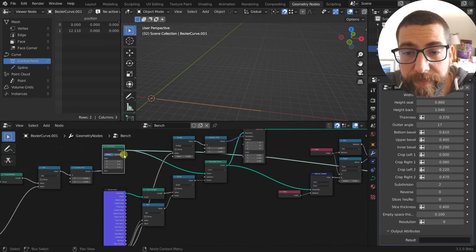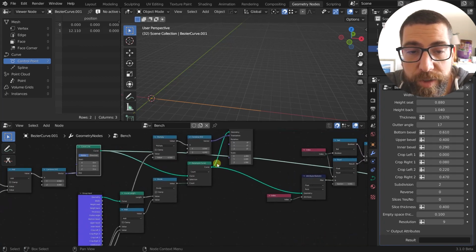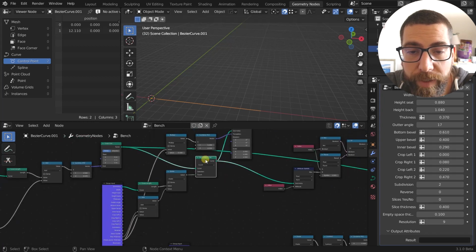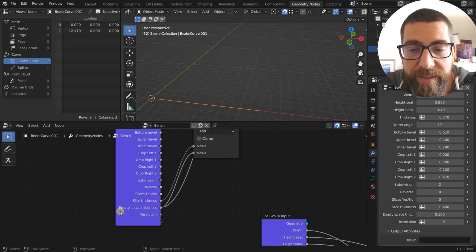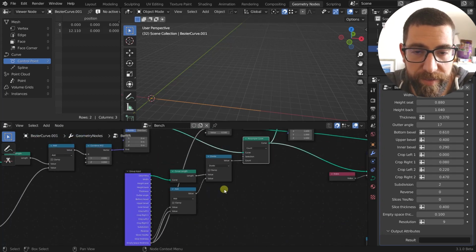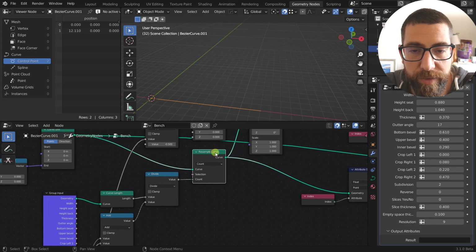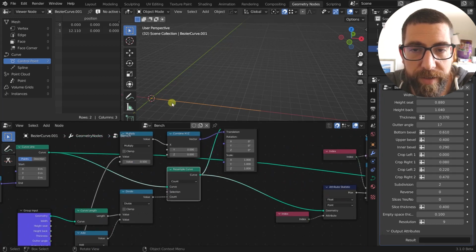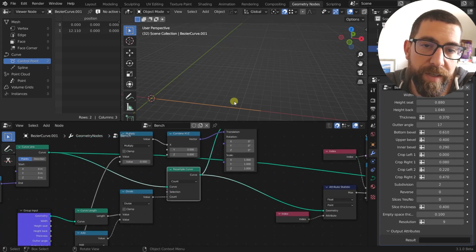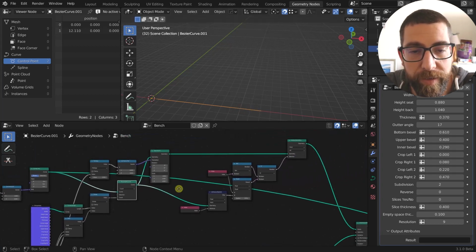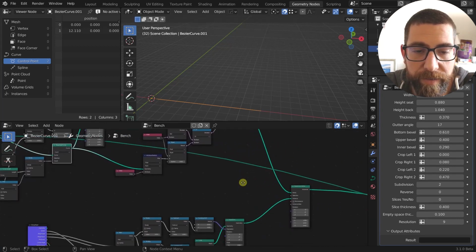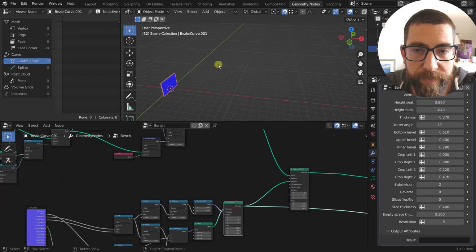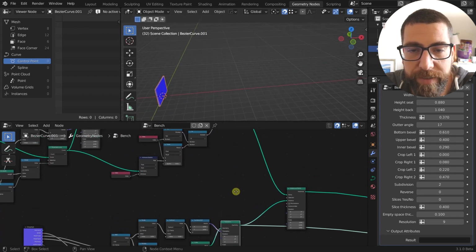It's the same line, but this time it needs to be resampled in respect of the size of the slice thickness and the empty space thickness. So that's what we did here. So we resampled this line so that its vertices come out spaced the right amount, so that we can instance our cubes on it and create slices.